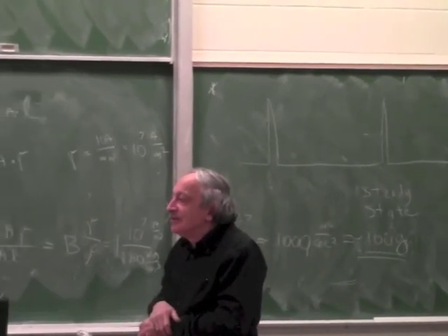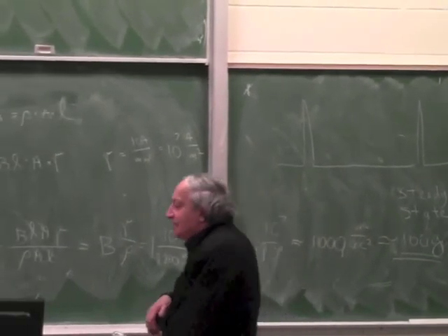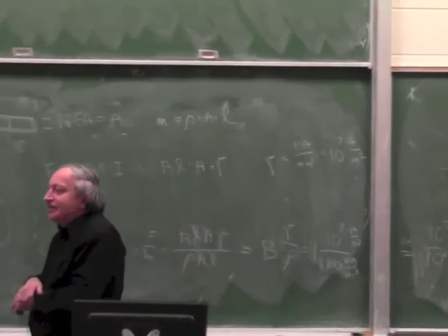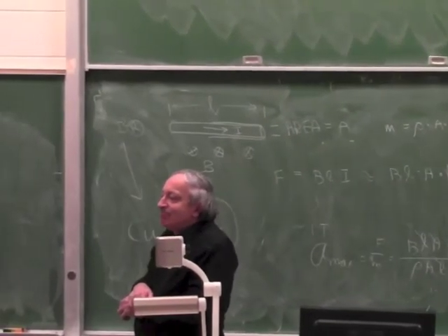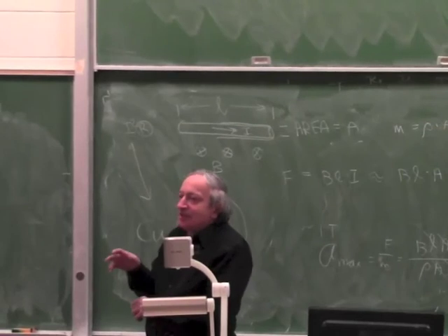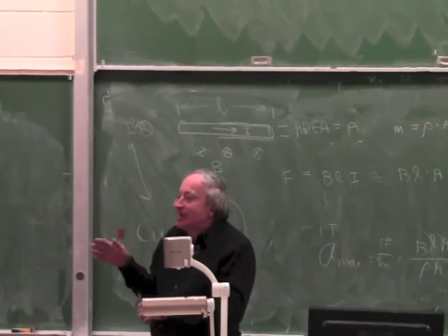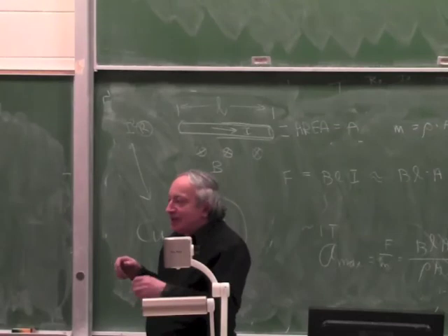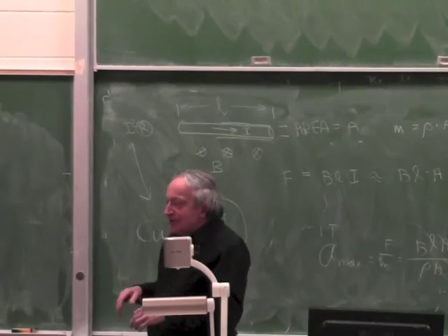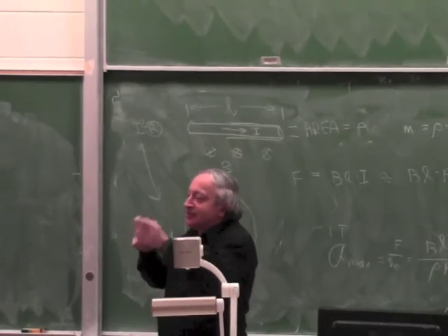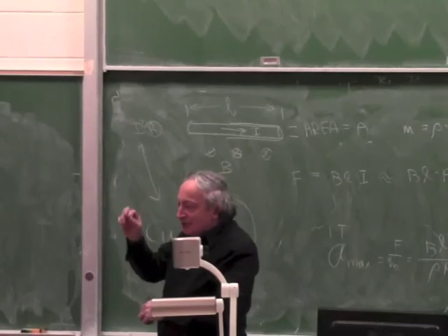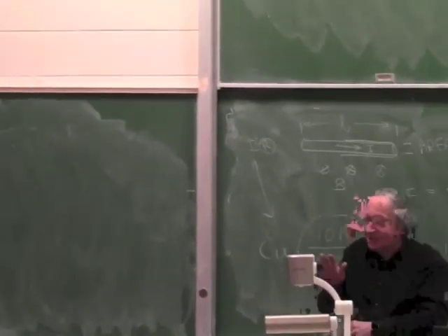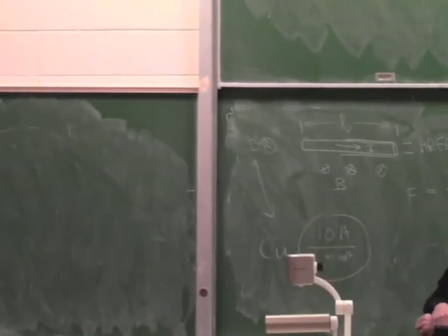The tension limit of the insulation material? Say it again? The maximum tension you can go between the 2 layers of insulation? Again, I can get around that. You're talking insulation limit, but I can get around it by making it with very high current, very low voltage. Let's say I make a coil which only has 1 or 2 turns, and I drive it by thousands of amps. So there's very little tension difference or potential difference. So this I can get around. This is actually not a real limit.